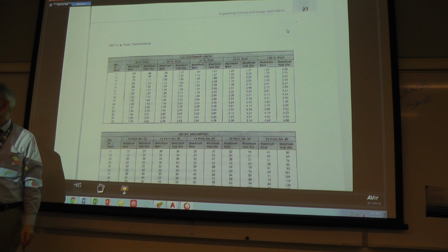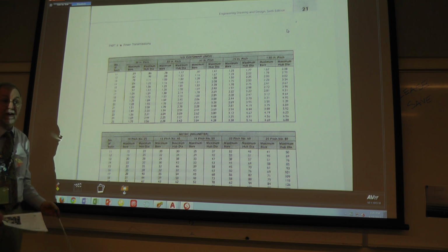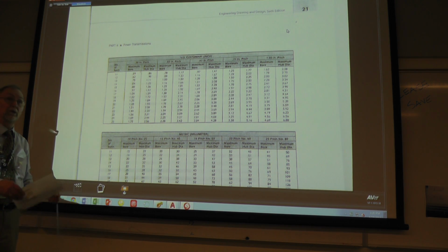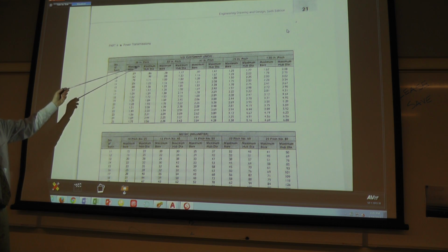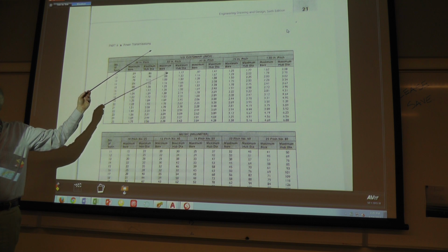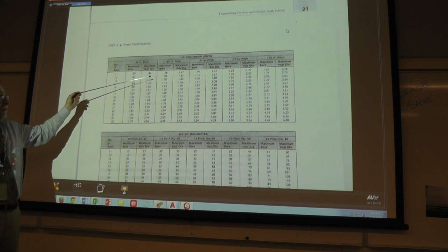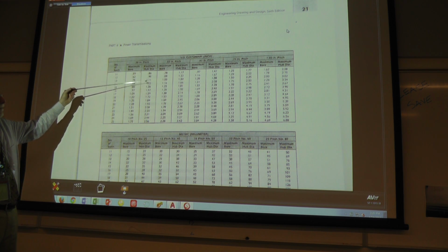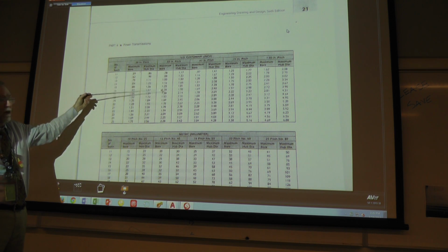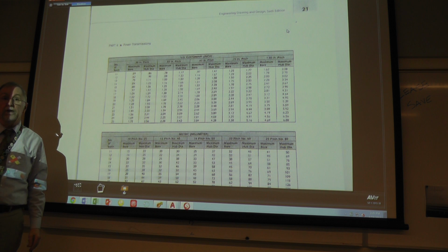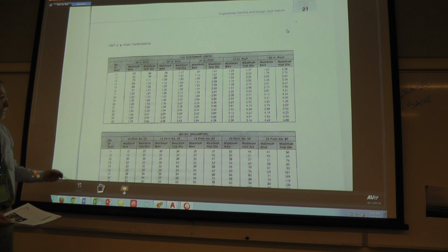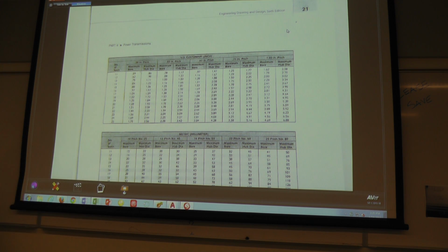maybe custom make a sprocket that has the ability to take that kind of bore. Or get a motor that's got a smaller shaft to it. Any number of things could happen. So, question? Or mill the shaft. Well, yeah, I mean, there's things that can be done, but basically if I can stay within this maximum bore in finding a supplier that has a sprocket, I'm much better off. And so that's a metric down below that.